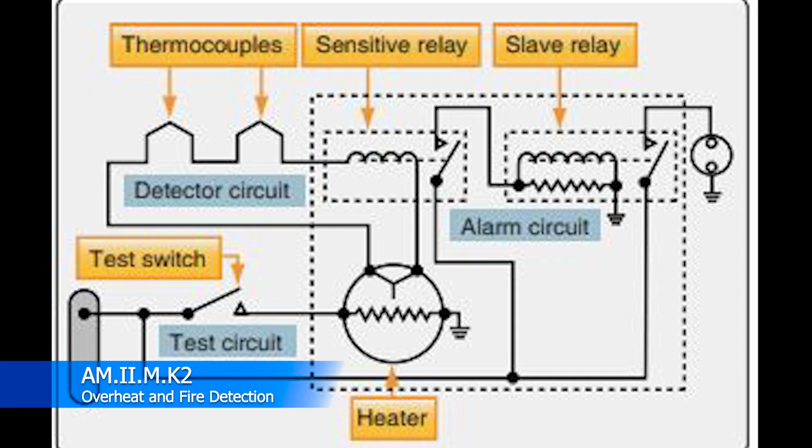What ends up happening is you have two different circuits that will be exposed to heat. Those two different circuits and their exposure to heat will create two different voltages that then are compared. What the thermocouple system is looking for is a differential in those two voltages by a significant amount.